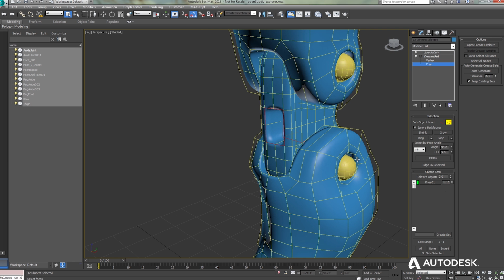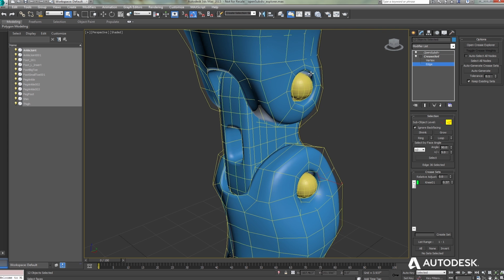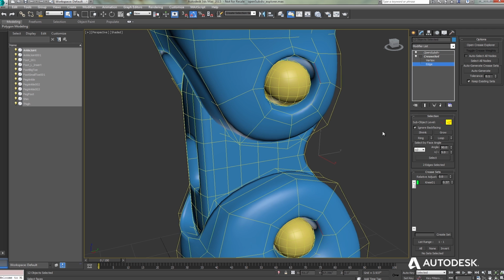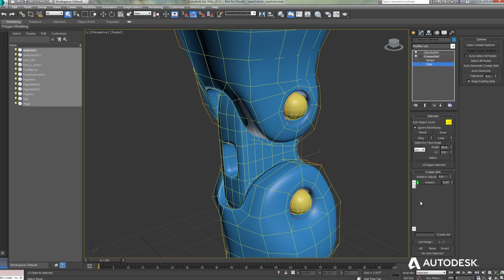Now what we can also do is select some additional parts that we want to add weights to. We'll say, for instance, these side joints, and then we'll make a new set and call those the pivots, and then we can increase those weights as well. Now what you can do is select both these layers and relatively adjust their weights as well. Lastly, when you right click, there's a bunch of different controls here. You can rename the layer, you can delete it, delete empty sets.